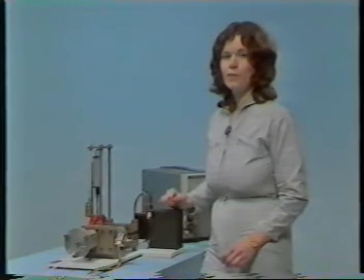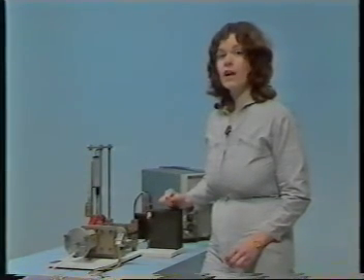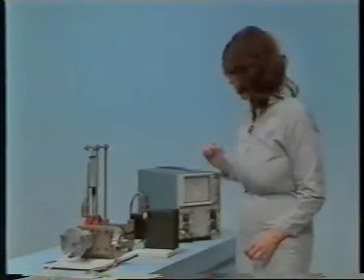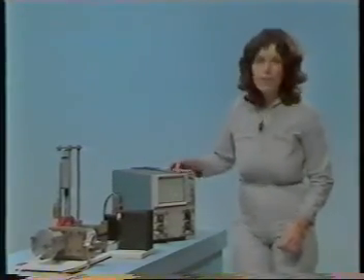Tony's already shown you the ideal pressure volume diagram for the Stirling cycle. Here's the reality. This is the PV diagram for our engine. Compare that with the ideal, the constant volumes and the isothermals. And remember that this area here represents the work output during one cycle.